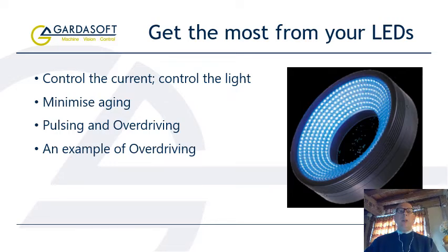Driving an LED continuously will generate the most heat and create the lowest device lifetime. Switching the light on only when an image is being acquired by pulsing the light will minimize the amount of heat produced and significantly improve LED lifetime. Pulsing can be achieved most easily by using a lighting controller to manage the strobing.